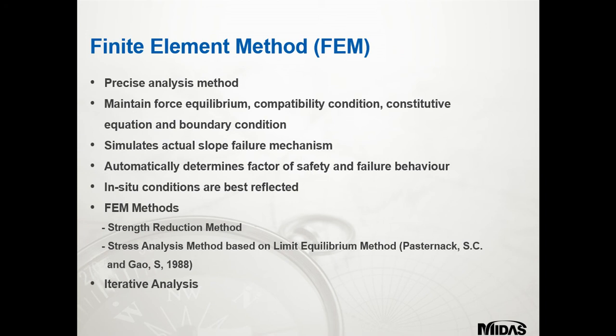It simulates the actual failure mechanism and automatically determines factors of safety and failure behavior in the slope based on nonlinear analysis. In situ conditions such as pore water pressure profiles and other things of that nature can be best reflected in finite element analysis modelling.